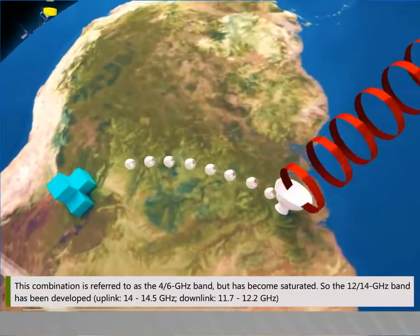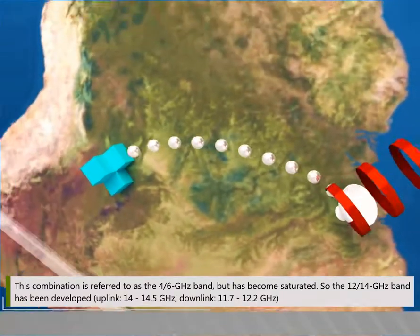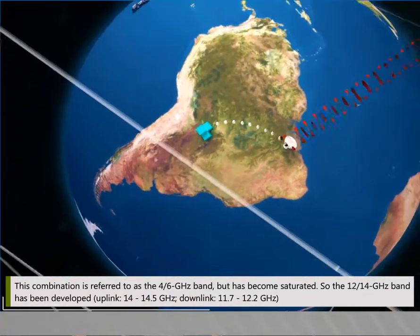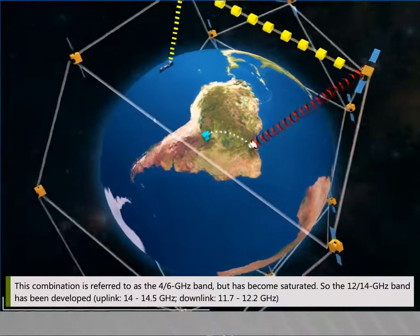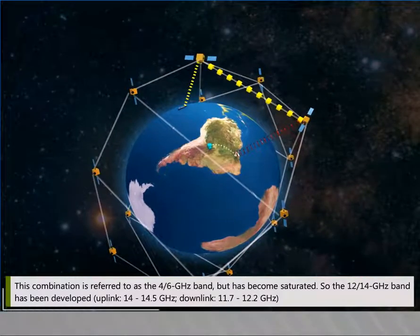This combination is referred to as the 4x6 GHz bands, but has become saturated. So the 12x14 GHz bands has been developed. Uplink 14 to 14.5 GHz, downlink 11.7 to 12.2 GHz.